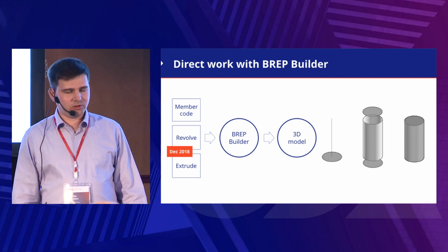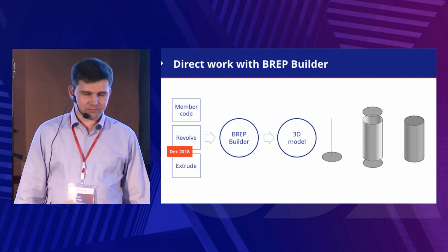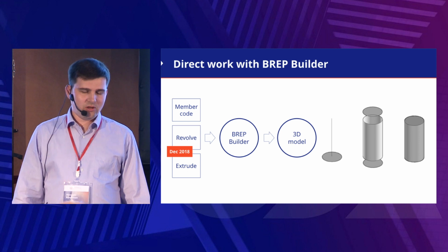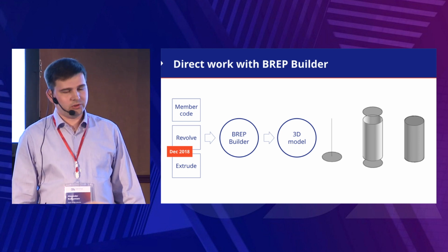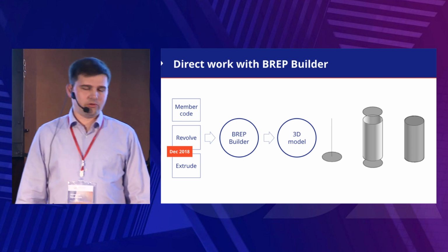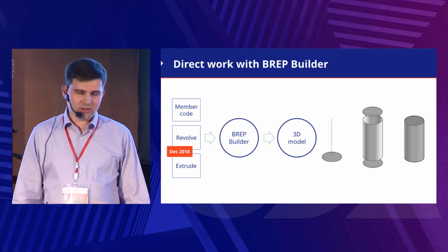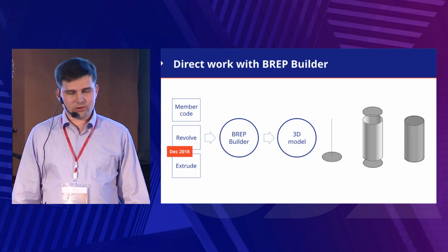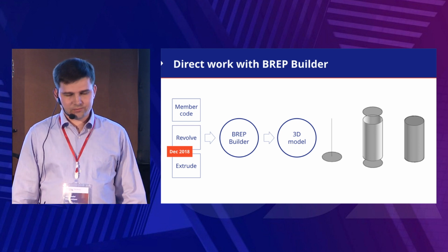But what about direct using of the BREP builder interface? Yes, it is also possible, and in December we will release Revolve and Extrude modeling operations for Drawing SDK, and the implementation of Revolve and Extrude operations works via direct access to the BREP builder interface.